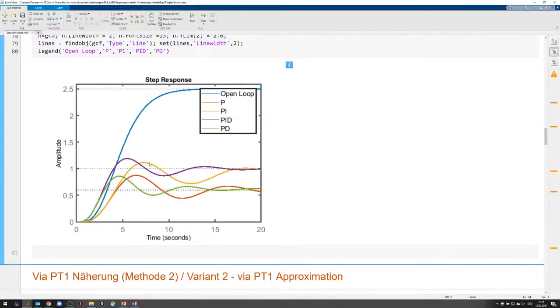However, I would not call this perfect controlled behavior. They are definitely oscillating quite a bit. So I'm not sure if you would be satisfied with such oscillatory behavior. However, this control method gives you a good starting value, and now you could say, okay, I want less oscillation, so probably increase the D term a little bit, because this usually damps your system.